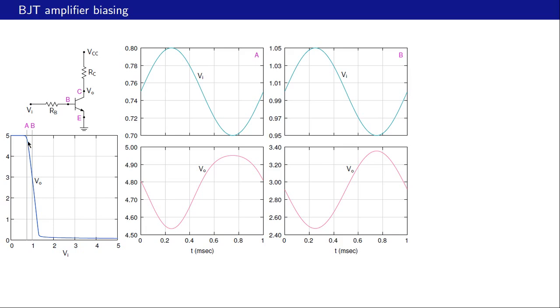If we go to the right, there is some gain, and if we go to the left, the gain is much smaller. The derivative here is much smaller, and that is reflecting basically in this distortion. This situation is definitely not desirable, and therefore we will not operate the amplifier at this DC bias.